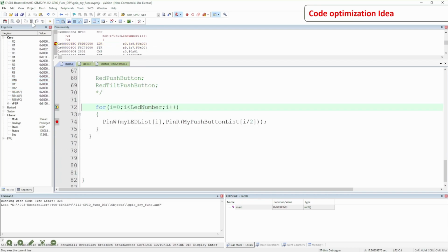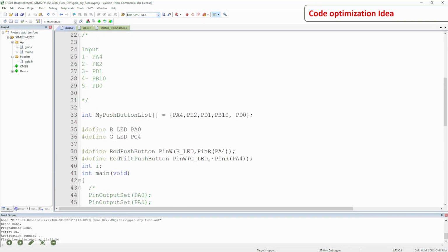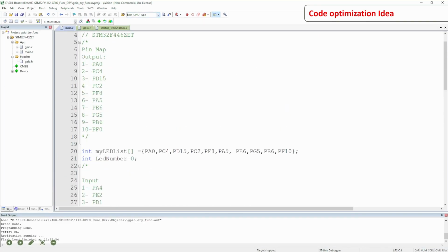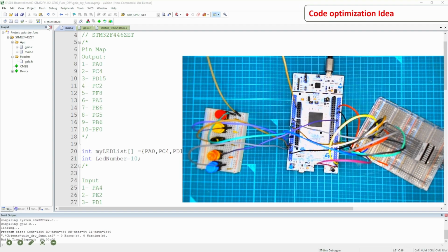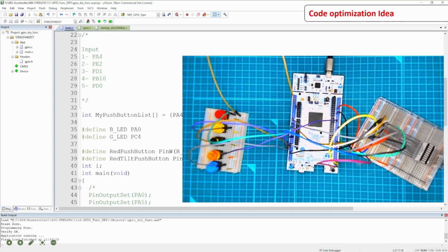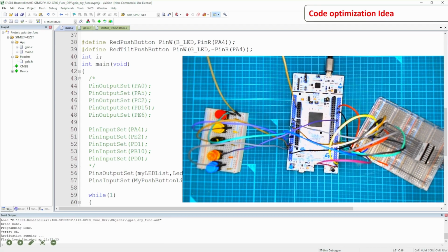So how I found this: the loop never goes inside. That's a mistake. You probably saw it when I was writing the code, but by debugging, I see that the for loop never goes inside. And just by clicking here, I see the LED number is equal to 0. Yeah, it's a dumb error, a Sunday error. Okay, let's save, build again, bring back the video, and load. Hope now all is good.